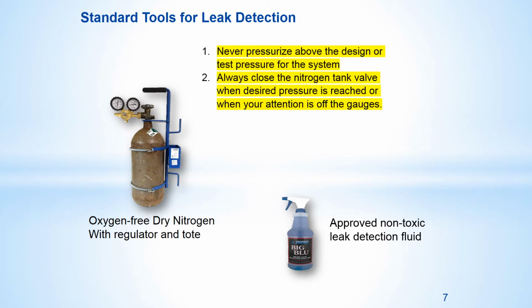Always remember, never pressurize above the design or test pressure for the system. Always close the nitrogen tank valve when the desired pressure is reached or when your attention is off the gauges. This is for your safety as well as for everyone around you. If used improperly, this equipment is dangerous. But when used correctly, following the procedures outlined in this training, it will save time during diagnosis and time during repair.